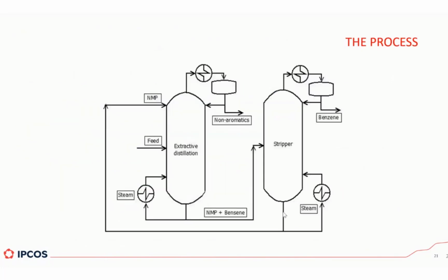So this is basically an overall view of the system, of the process. You see, you have your solvent coming in here. You also have a reflux coming in. So you have both, and this is when you need to start thinking, okay, this is not your average distillation column, because you have a solvent, but you also have a reflux. And there is a tendency for people to believe that, because this solvent is coming in the top, it's doing the same thing as a reflux is doing.